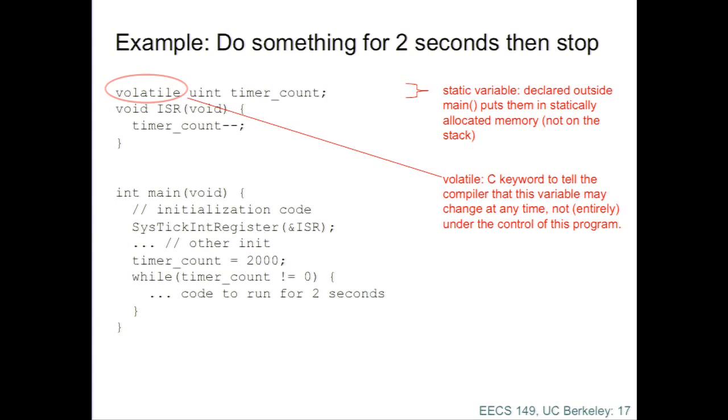In the case of the Xilinx processor that you'll be using in the lab, that interrupt request will be ignored until you've returned from interrupt. At that point, depending on the hardware, the request may still be there or may not. If the voltage is still high on the interrupt request line, if the timer happens to hold it high long enough, then you might get an interrupt handled late. But if the hardware doesn't hold the request up long enough, the voltage has gone back down, you could return and the interrupt just gets completely missed.